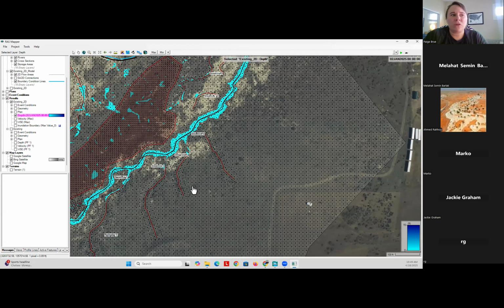If you don't have terrain data for the cross sections upstream, or if it's a really big stretch of stream where the runtimes would be obnoxiously long, that would be a situation where you might want to use 1D, 2D. But yes, combining 1D and 2D is annoying because of that interface between 1D and 2D, where RAS is trying to change equations. It's finicky and it can take a while to get right.